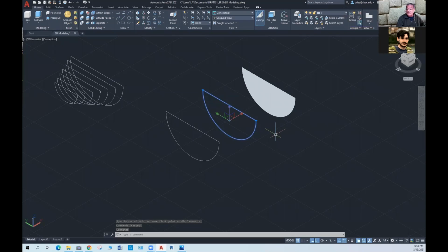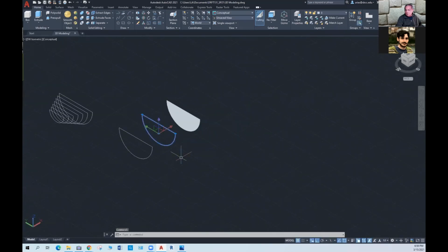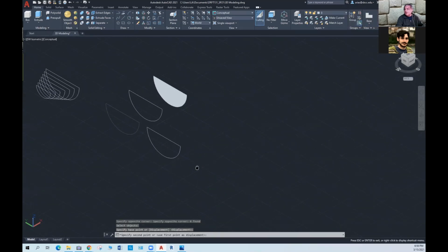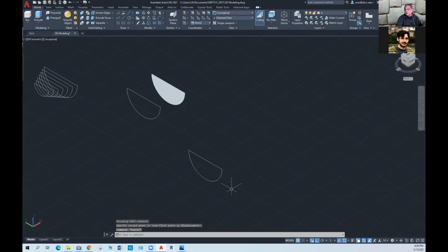So whenever I have a hard time trying to create a polyline with the objects, I can use the hatch to create a boundary. And by definition, that boundary will be a polyline. And that's what I wanted to do. And so you could then use this object again to create geometry that you may need.